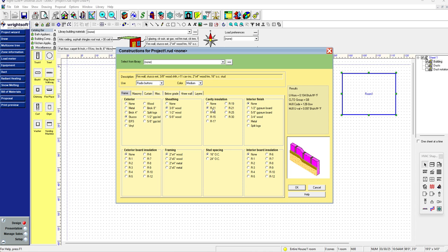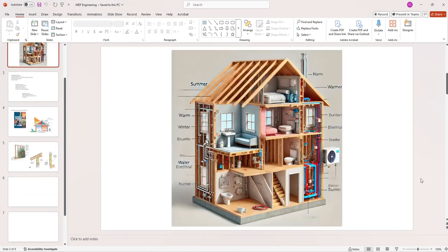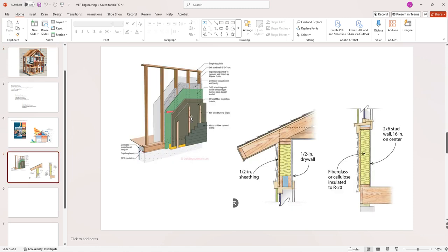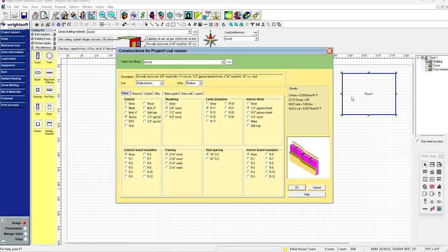I would double check that though. So that's the insulation that goes between each wood stud. And then on the interior of the wall, there's most likely some sheetrock, as people call it colloquially here, although I think that's even a trade name. The proper name would be gypsum board, all right? There could be other insulation, as I showed in this image here. This would be additional insulation. That is done sometimes, and you would specify the R value of that other insulation.